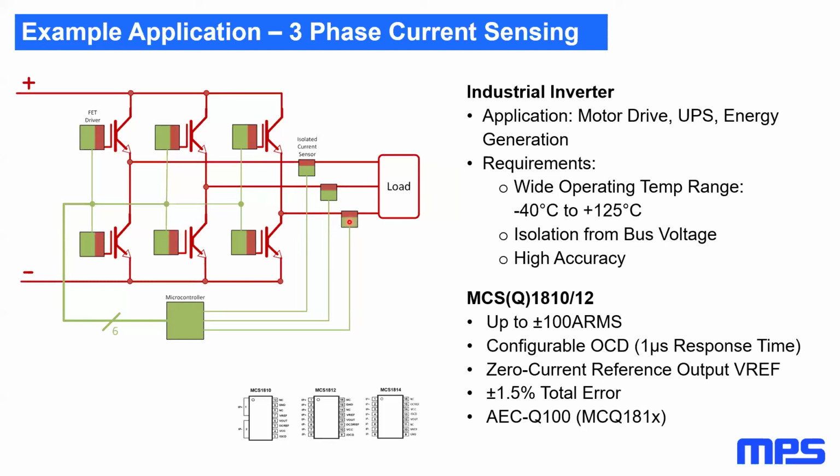And what we don't want is that phase 1, which does create magnetic flux, as we know, interferes with the sensor on phase 2, and phase 2 doesn't interfere with phase 3, and poor phase 2 is getting it from both 1 and 3. And so we have to be able to reject these fields. Now, there's ways to do that geometrically.